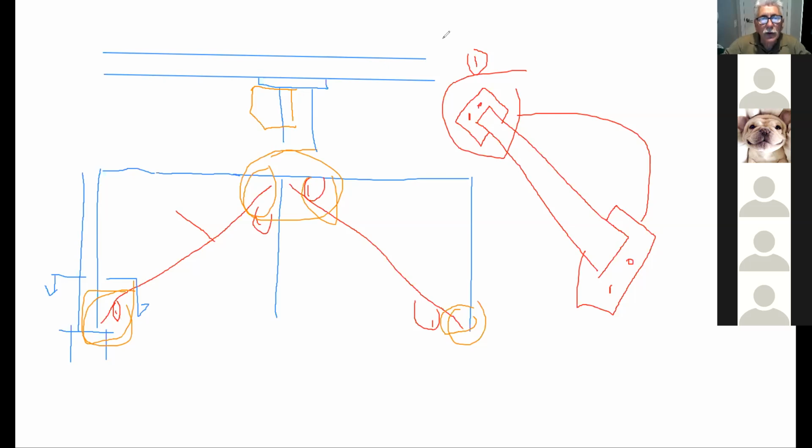So in other words, you want to make sure that, for example, when the wind, the lateral force, is coming here, it goes through your roof diaphragm and then it hits here. It's going to go through the connection here and then go through this connection here. Yes? And then all the way down here through this connection here and eventually get transmitted to your foundations.